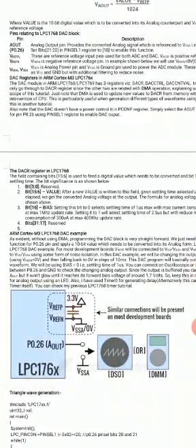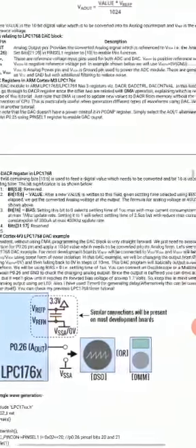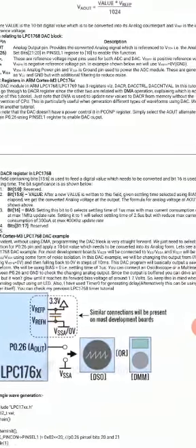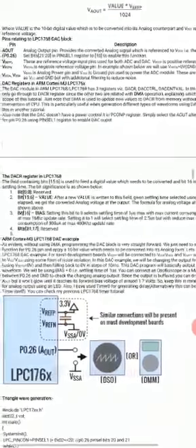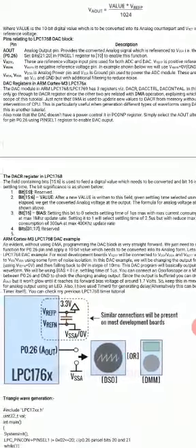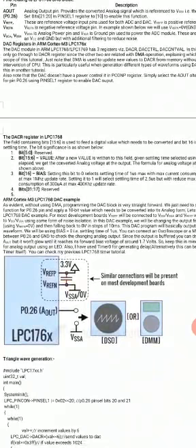Bit 16 is the bias; setting this bit to 0 selects a settling time of 1 microsecond, with a maximum current consumption of 700 microamperes at a maximum 1 megahertz updating rate. Don't worry about bit 16, which we usually keep 0 so that it produces a 1 microsecond settling time.